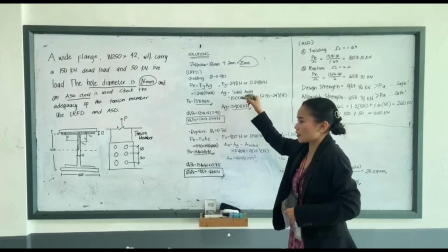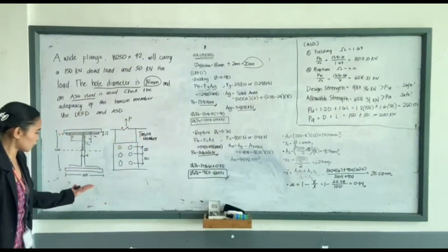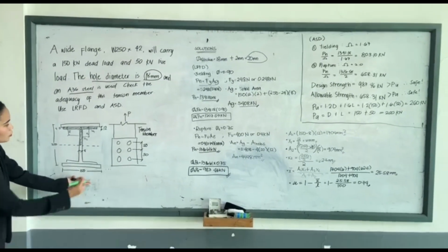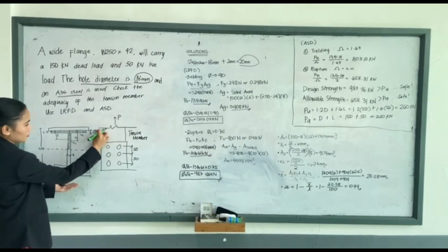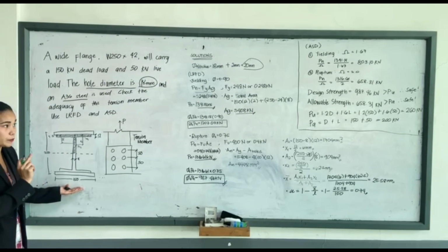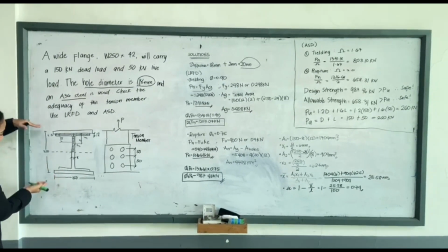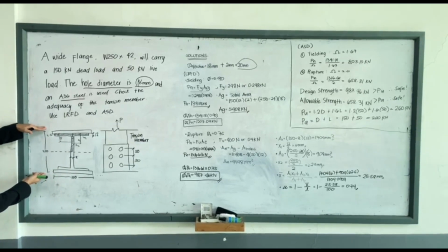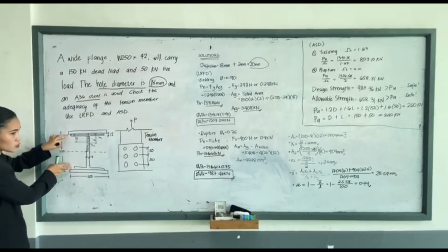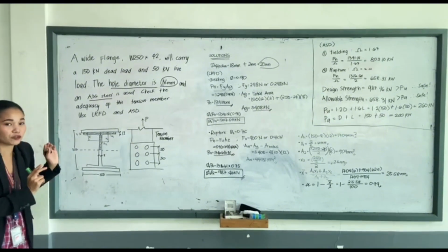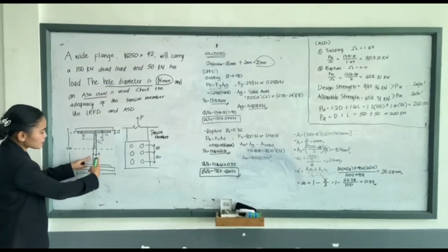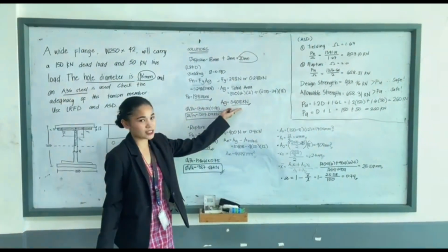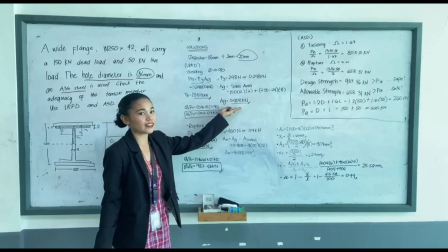So we look at the illustration of the flange. It has a base of 150 times its thickness of 12. Since there are two flanges, times 2. Plus the web area, where the height is 250 minus two times 12, which is 24. So 250 minus 24 is 226, times its thickness of 8 mm. So we get an area gross of 5408 mm squared.